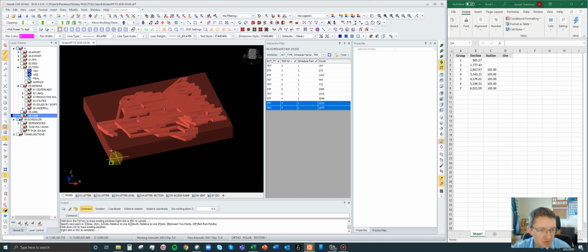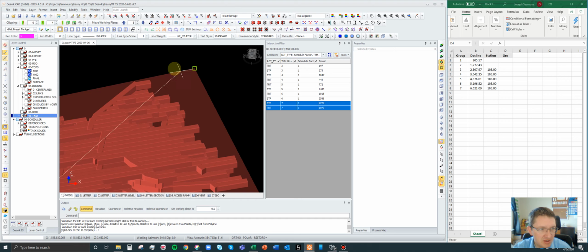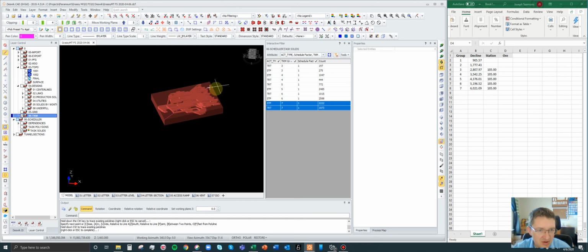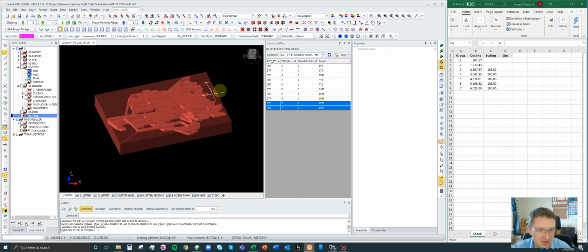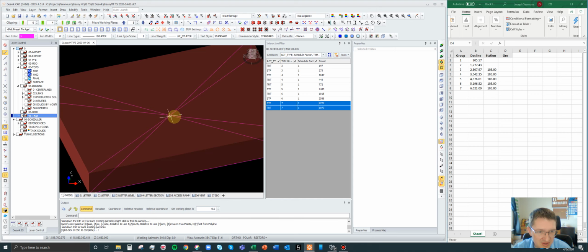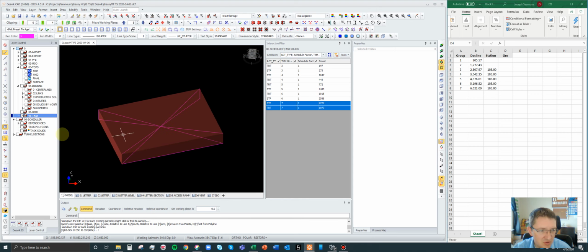I'm going to turn off the midpoints. This is your snapping over here. I just want endpoints. So there's the top one, there's the bottom one. Now you see the middle of that. I could do it again and go like this, and again like this, but you only need one. Because you see how the midpoint for all of these is going to be the center. And that's what we're going to use to measure from here out. Okay?